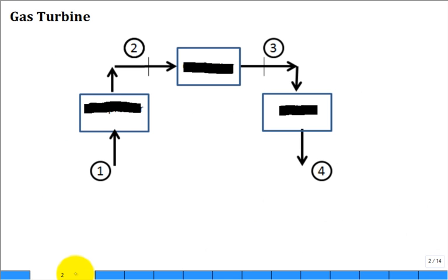So what are the major components of this gas turbine? Well, the first one was the compressor. What's the object of the compressor? To get P2 much greater than P1. And this is a very difficult tongue twister for us. Coming off of the Otto and diesel, we learned about the compression ratio. You would think that the compressor would specify a compression ratio, but it doesn't. What is specified for the compressor is the pressure ratio. So the pressure ratio would be P2 over P1, and maybe that's 9 or 8 or 17 or 12.